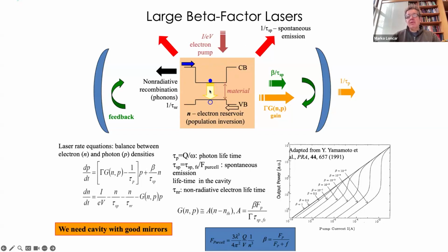That's not very good. But maybe some fraction of the spontaneously emitted photons goes into a cavity, an optical resonator, which is basically a waveguide with some mirrors at the ends. The photon hits the mirror and gets reflected. This medium is pumped again, so there are more electrons in an excited state. They get stimulated to emit, so you get stimulated emission. Now these two photons travel together, hit another mirror, and this process continues. So what you need is feedback and low loss: a low-loss waveguide, mirrors to provide feedback to turn spontaneous emission into stimulated emission, and a gain medium that can be pumped, ideally electrically, to build a laser.